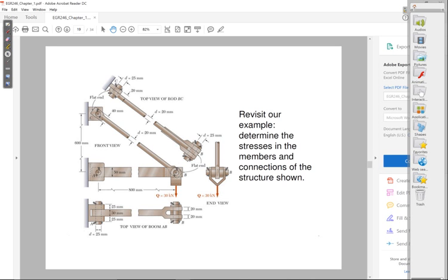And then you have something very similar that goes on at joint B. Joint B is more complicated because there's an applied force of 30 kilonewtons pulling down. But again, it's all pretty much the same thing. You have bearing stresses and shearing stresses on the pin and on those holes. All right, so take a look at those details on your own if you're up to it. Otherwise, it's not even necessary.